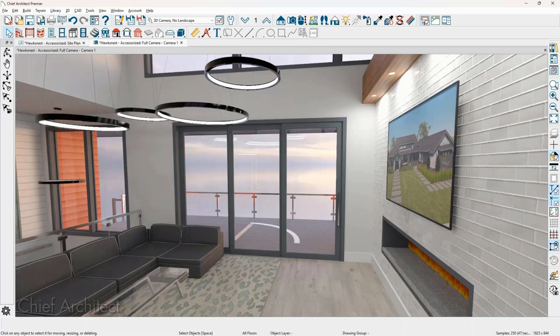If you have the checkbox unchecked so that sun is not just coming from the backdrop and it's actually coming from the defined sun that you've set up in your walkthrough, it will change lighting and it'll change where the shadows are going to come down, but your backdrop will stay the same throughout that walkthrough.